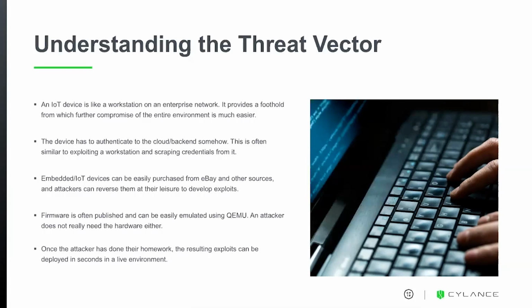A final takeaway is that in some cases, we don't even need the hardware. The hardware is what the code runs on, but firmware makes its way out there and is often published by the manufacturer, made available on their website. And if you have the firmware, we can emulate this using a tool like Qemu and perform both static and dynamic analysis against it to find vulnerabilities without even needing the hardware to exploit it.